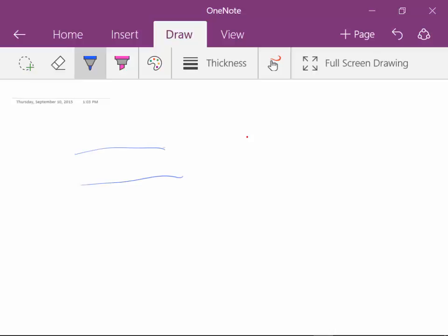we have some data changing right here. Here's a bunch of inputs to our flip-flops. Here they all change, and they have to change here, and then here's our clock edge. We don't allow any change from this time to this time. Our setup time, and then our hold time.